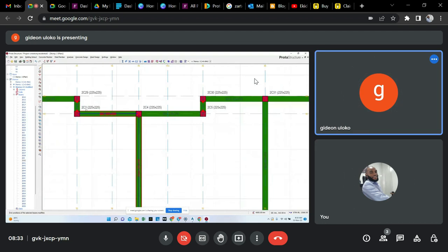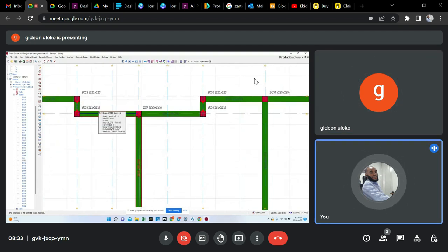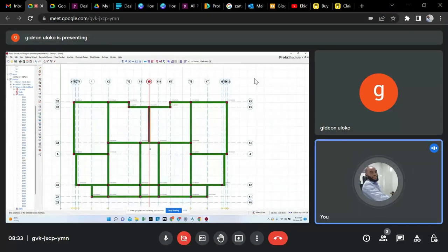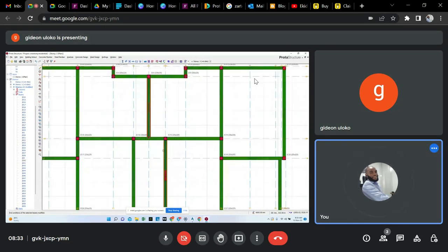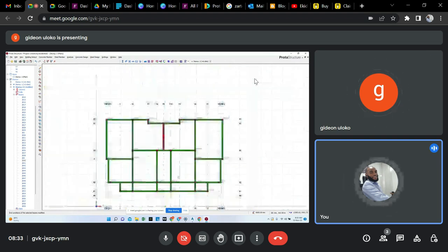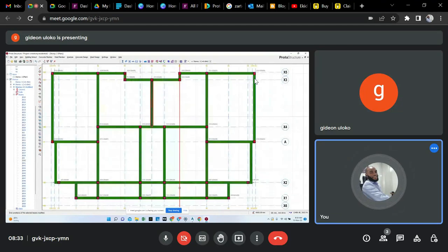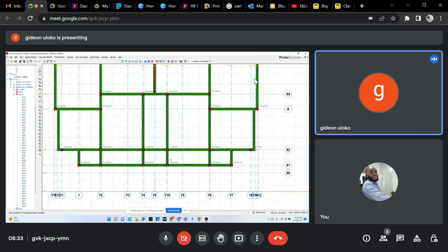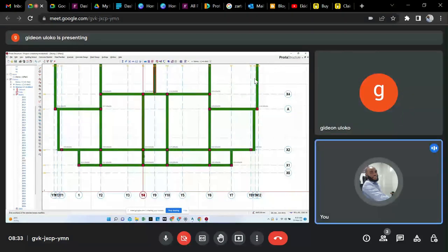These small ones? No, below. Yes, the two small ones at the ends. Those two simply supported beams, grid line Y7 and grid line 1, vertical. Yes, those ones. They are simply supported beams, so they should be hinged.